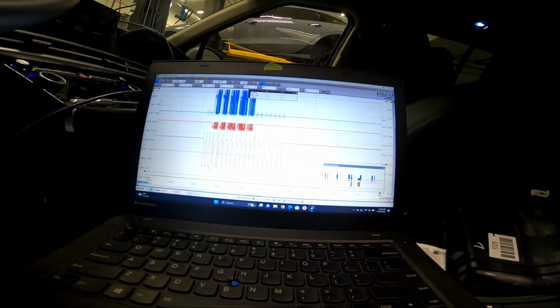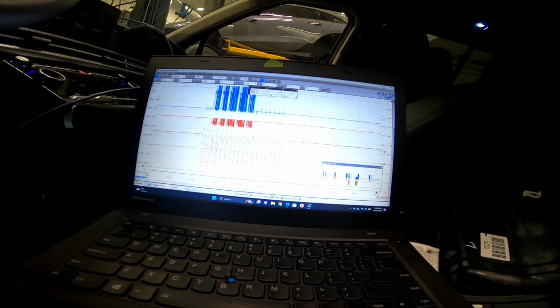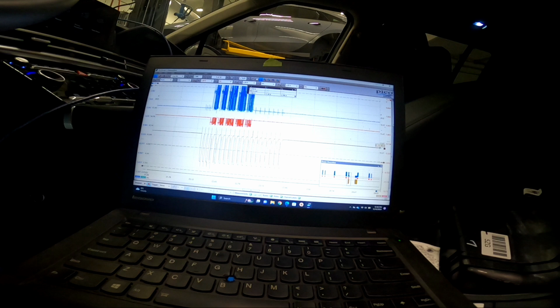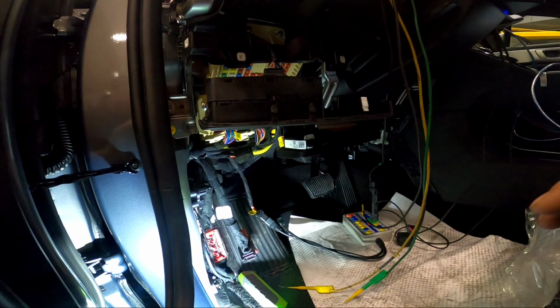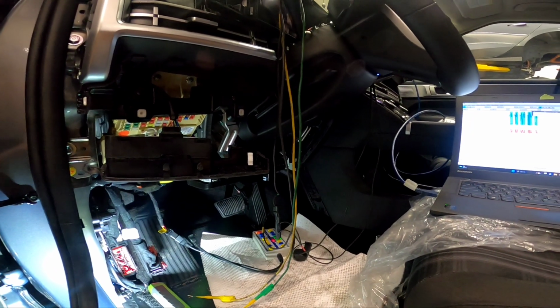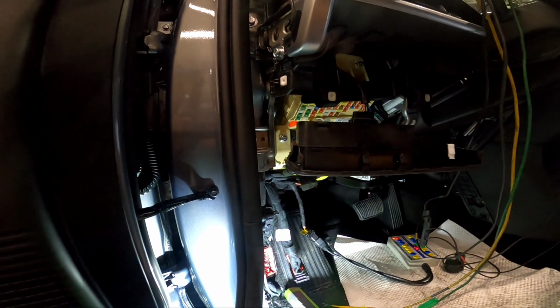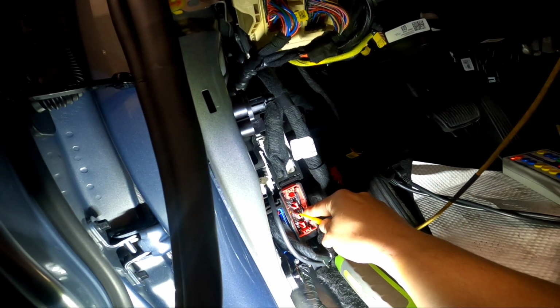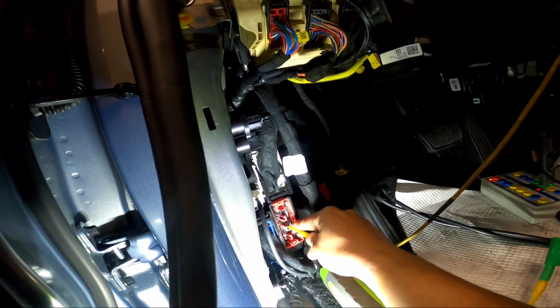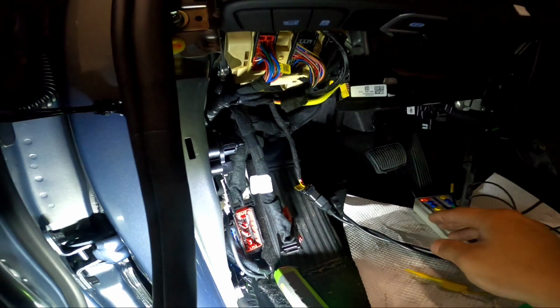All right. The yellow part is starting at 11 volts. So something is not correct there. That's the top one, that's going to be our CAN high, I think. So I'm going to go to CAN low now. Oh no, that's the CAN low. This is the CAN high. And yeah, it shows the same too. Battery voltage in there.